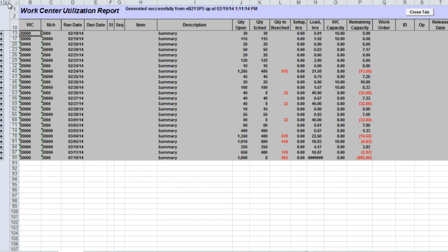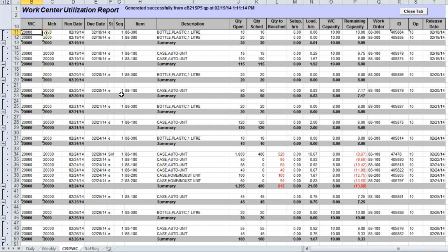In this report, Work Center load for each item and operation is calculated based on a standard item routing. Start date for each operation is calculated forward from schedule date, taking into account operation move, wait, subcontract, run, setup, and queue times, and required overlap quantity, if any. Available work center capacity is identified for each operation start date based on the shop floor calendar and a number of machines per hour. Work center capacity is consumed by operation based on their start date and item sequence.